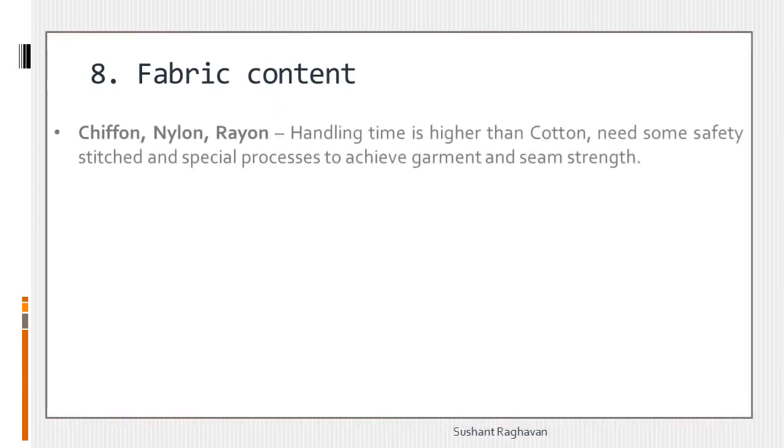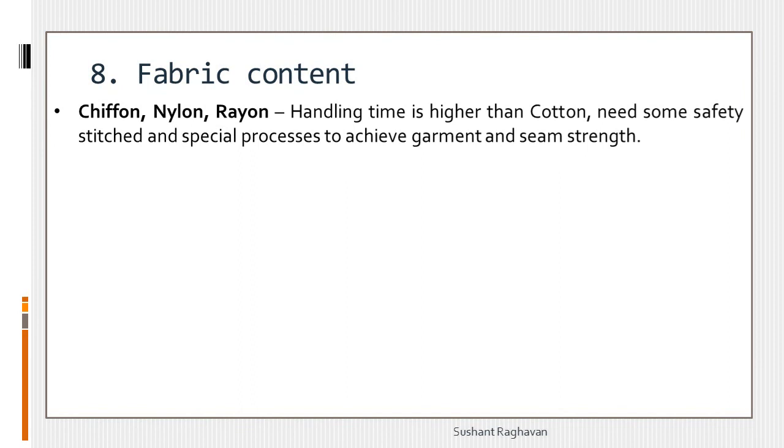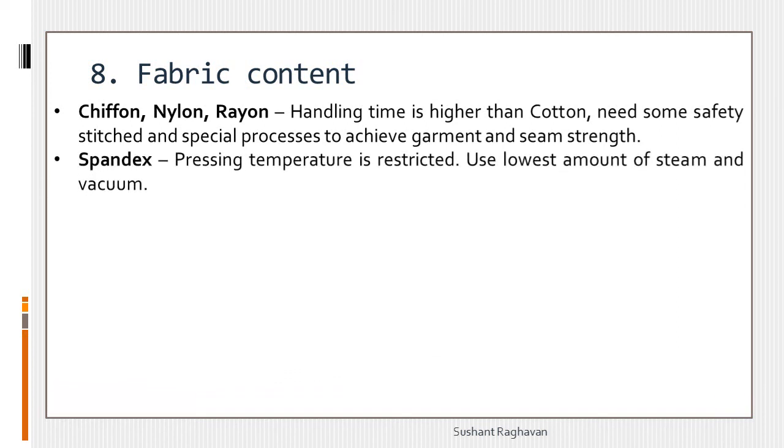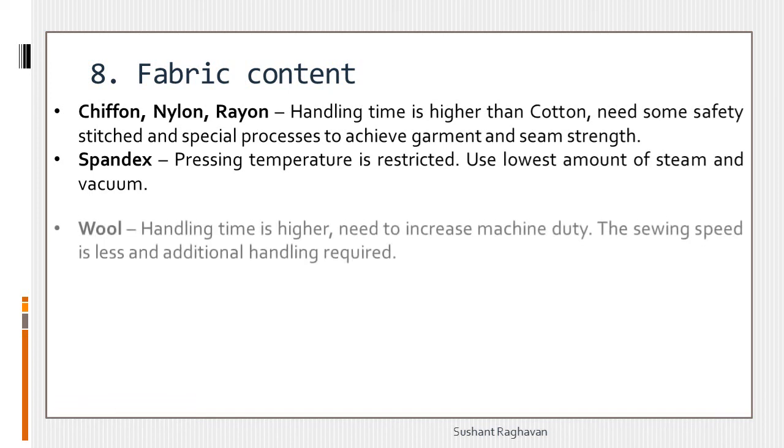Fabric content. Chiffon, nylon, rayon: handling time is higher than cotton. Need some safety stitch and special process to achieve garment and seam strength. Spandex: pressing temperature is restricted. Use the lowest amount of steam and vacuum.